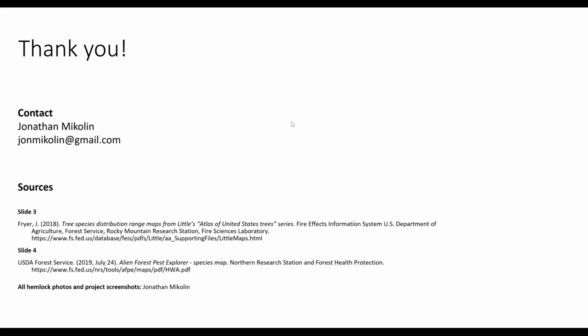All right, thank you, Jonathan. Very interesting, very nice presentation, very nice demo actually. You really explained the rule set in detail, and I really liked it. Especially for me, I must say at the beginning how you rework those image objects, right? Because usually a lot of users expect to have perfect objects after segmentation, but those are more or less really the building blocks, right? And then you can work on them, pixel-based object resizing, merging, then removing objects. So I really like that.